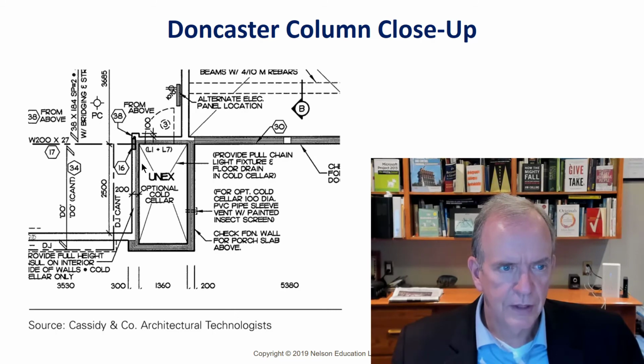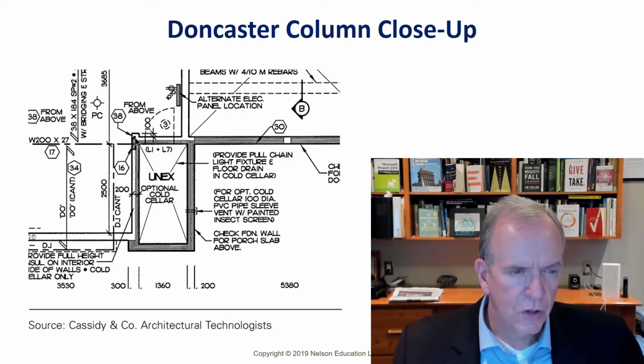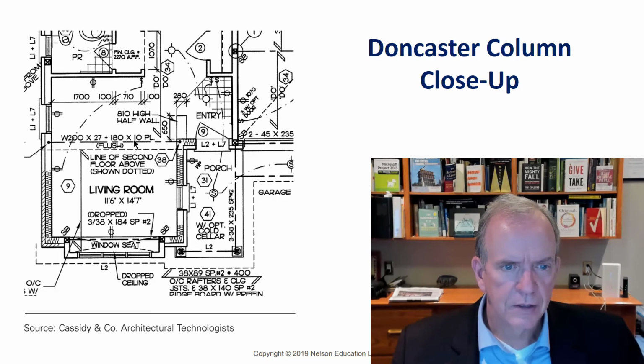Here's another interesting detail, because there's a lot of stuff going on, and if we have to build this, we have to think about the constructability quite a lot. So you have an I-beam that comes across, and it's in a beam pocket. You also have a little bit of an extension here. And there's a lot going on in this foundation. You got a little solid circle there. You got a steel pipe column that's coming down that's supporting a bunch of things. And on the floor above, there's the steel pipe column.